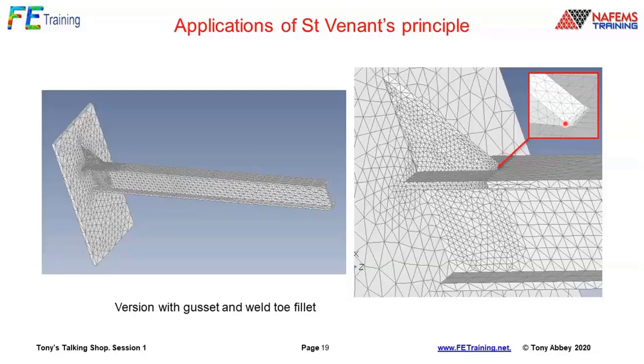I put a little radius in here. That's too locked in. We want to have a generic application. So what they do is they want to get rid of that stress concentration factor there, extrapolate the stresses through, and then, with the nominal stress back in again, apply a stress concentration factor which we bring from our practice and our principles, rather than getting stuck with whatever comes from FEA.